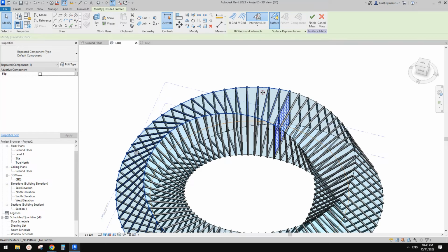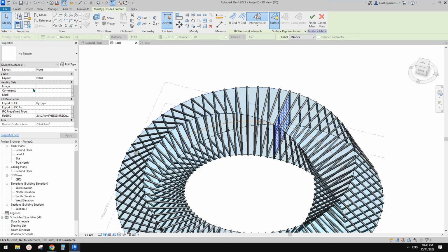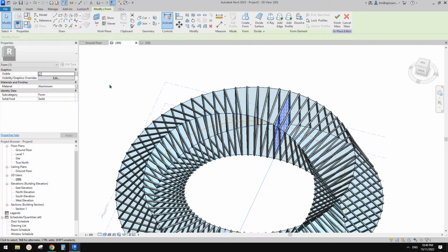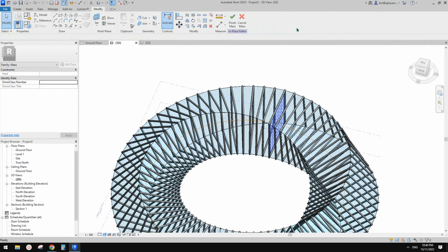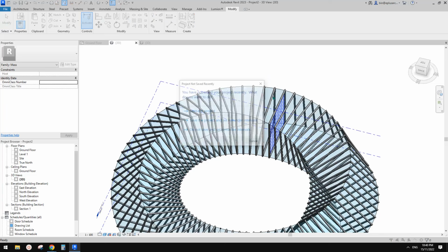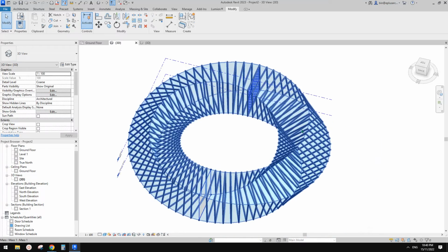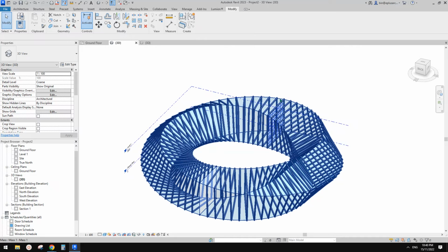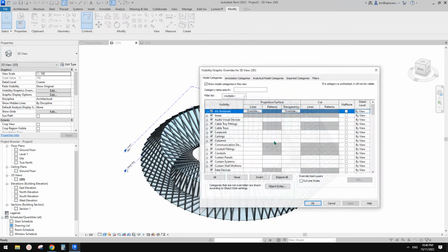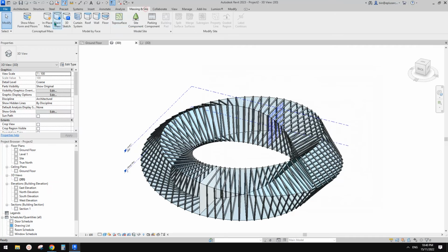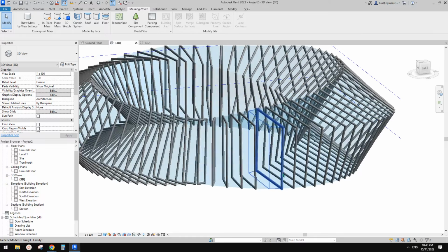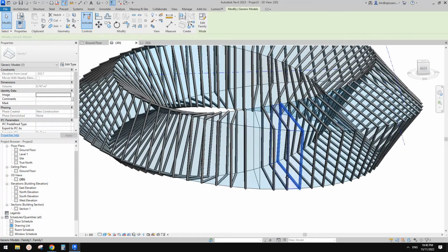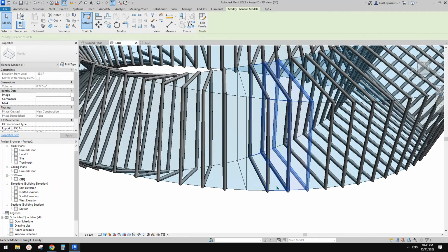So let me just have a try. Try to tab. Try to select. Yeah, select this. No, still default surface. Yeah, I think you can probably just use, or even don't worry about that, because we can always turn off the mask in the project. So this is a project. So these are the masks, and then you can just go turn off here. Yeah, I think that's it. So you can only see those adaptive families, which is the frame and the glazing.